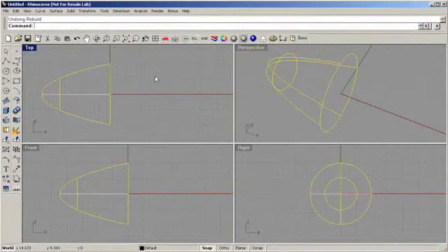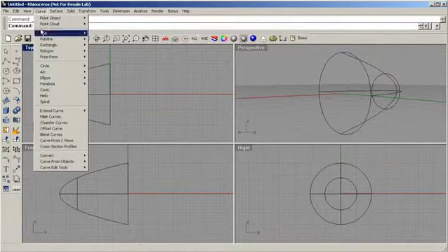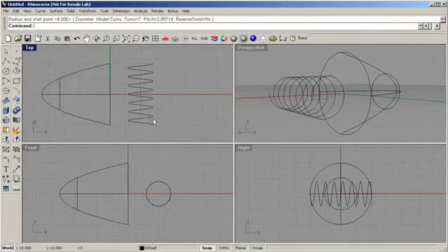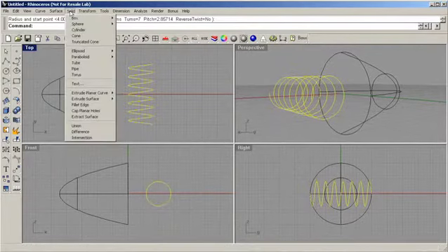Simple reflector. Next we'll construct a model of the filament source. Again I start by specifying a simple curve. Using the pipe option in the solid menu, we're going to turn this into a solid.